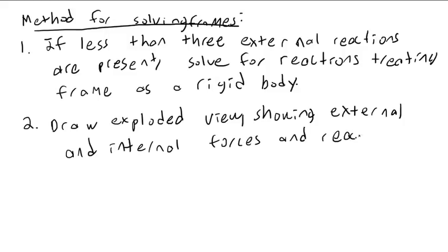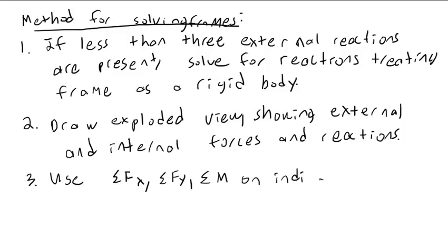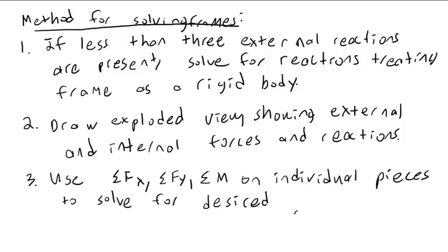And 3, use sum of forces in x, sum of forces in y, and sum of moments on individual pieces to solve for desired unknown forces, internal or external.